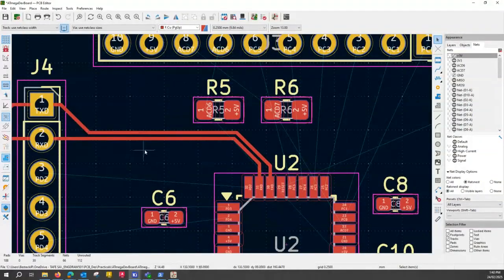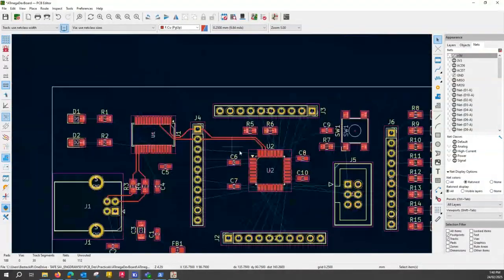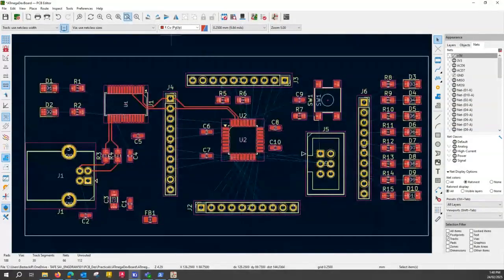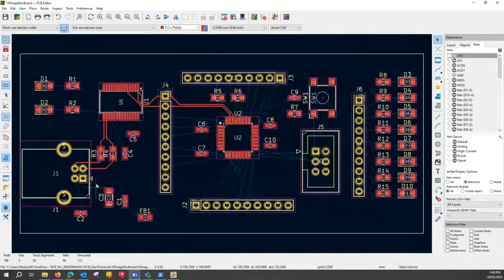So that's done. So this is the track which is communication critical. We always slide them first. We make sure that we don't cross to the other side of the board. You want to have them on the same side to direct through it, reasonably equal length.